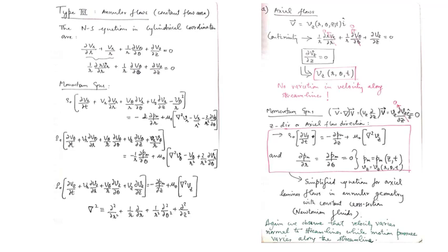So these equations apply to both types of annular flows that were shown a few minutes ago. The torsional type of annular flow that was shown, in which two concentric cylinders, inner and outer, were both rotating counterclockwise, was also an annular flow, and its passage area is also constant. And we also saw an axial flow, in which there is a pipe of larger radius outside and inside a shaft or another pipe of smaller radius, and the flow takes place in the annulus along the length of the concentric cylinders or pipes. So that axial and torsional flows both are covered by these cylindrical Navier-Stokes equations.